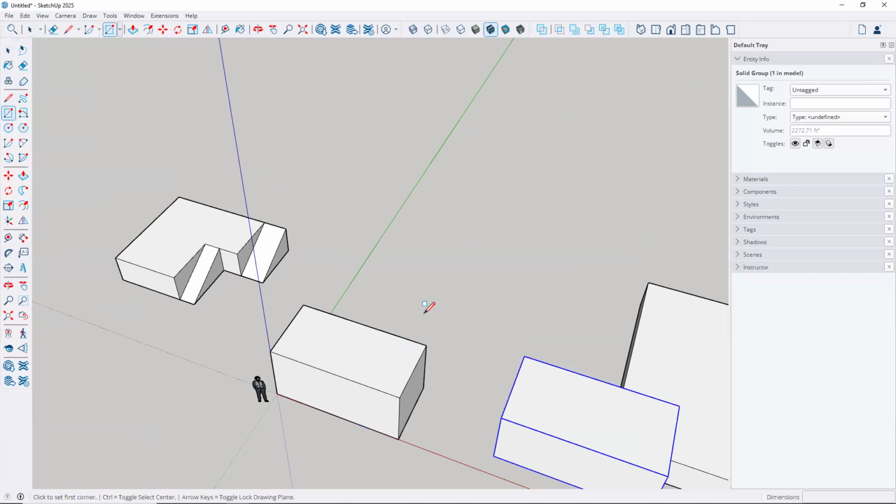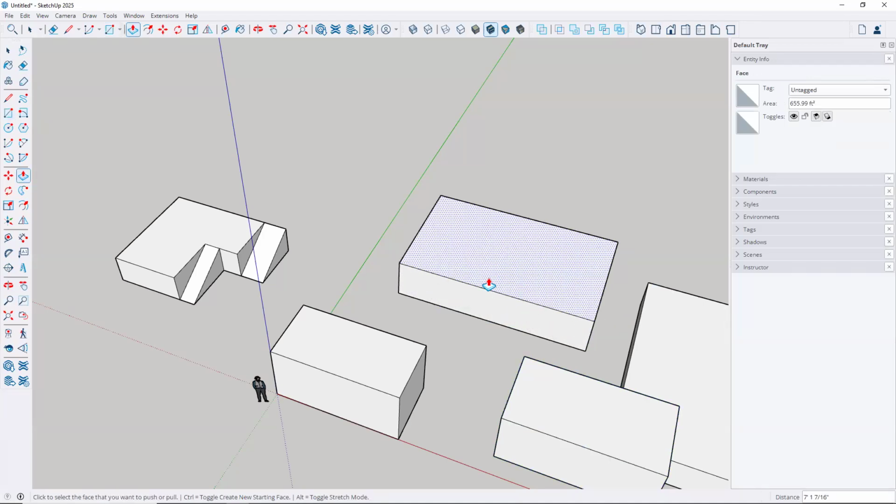So click on rectangle, and you can just draw a rectangle, any shape for now. And you'll notice with SketchUp, if I'm close to a square, it's going to give me a diagonal there, and it lets me know that that's a square. And I also believe it will allow me to do what's called the golden rectangle proportions, which is like 1.6. There we go, golden section. So that's kind of nice. I'll go ahead and give that a click. So it's a feature. Just know that. And then I can type P for push pull, raise this, and then always space bar, triple click, right click, and then make a group.